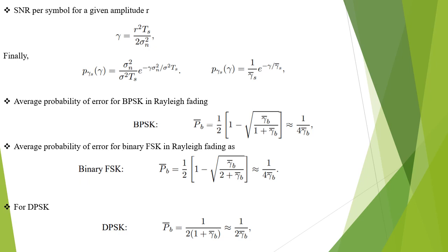However, in fading, the bit error probability for all the modulation types decreases just linearly with increasing gamma_b bar. Similar behavior occurs for non-binary modulation also. Thus, the power necessary to maintain a given Pb, particularly for small values, is much higher in a fading channel than in an AWGN channel.